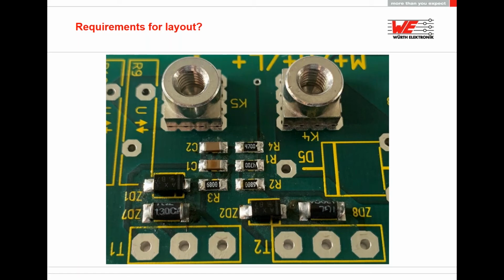All right. The second one is, we don't have a press fit process in the production. We would like to use SMD, THR and wave soldering. How much current derating needs to be considered with different material expansion and solder height to have a proper system?